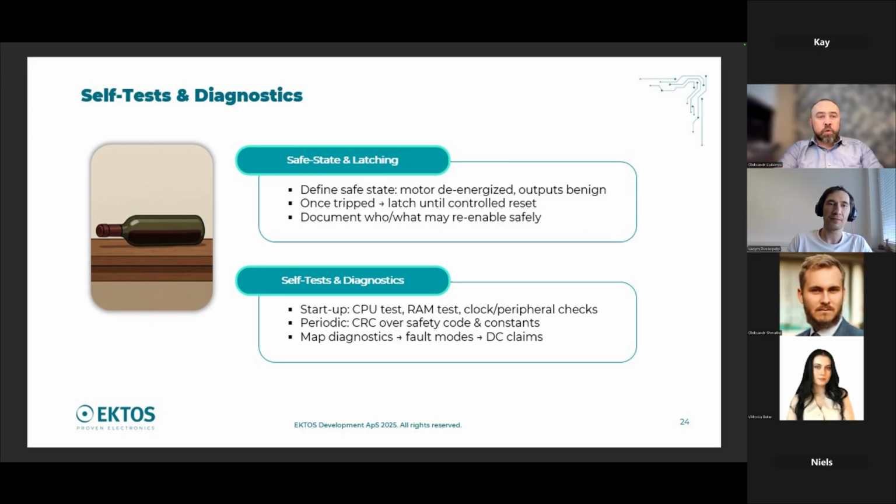For instance, Atmel and Microchip, which are now the same company, provide more or less the same processors where you can choose the microprocessor that has these tests implemented into the core. So it's some sort of peripheral. You can just hook that peripheral and say, now please test RAM.